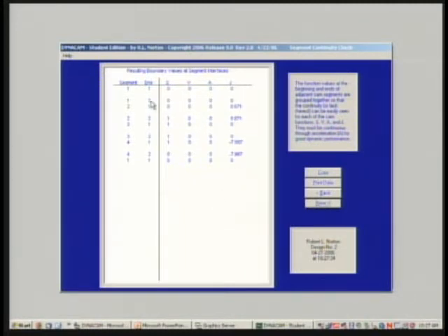What I've done is I've grouped the values of S, V, A, and J at the end and beginning of each segment together. This is segment 1, first end, second end, beginning, terminus. This is segment 2, beginning, terminus. So these two are the same point. The end of segment 1 and the start of segment 2 are the same physical point. They're at 60 degrees in this case.